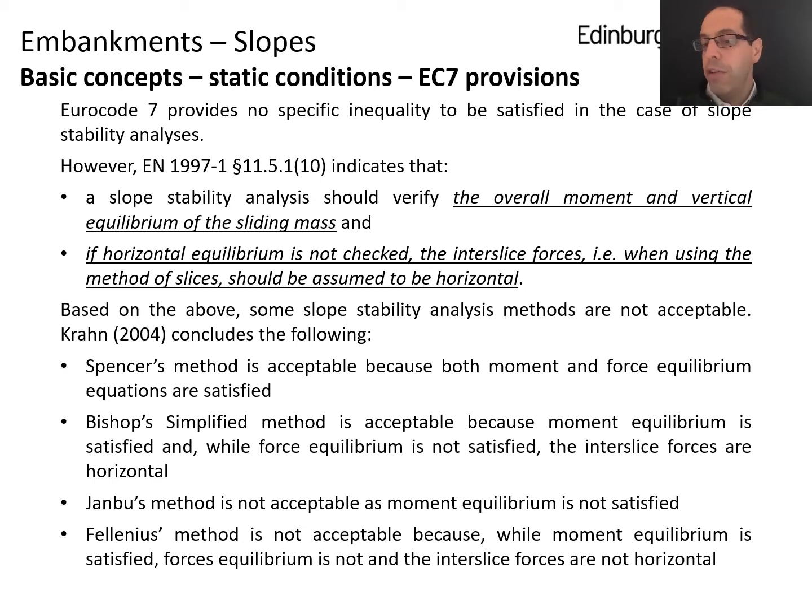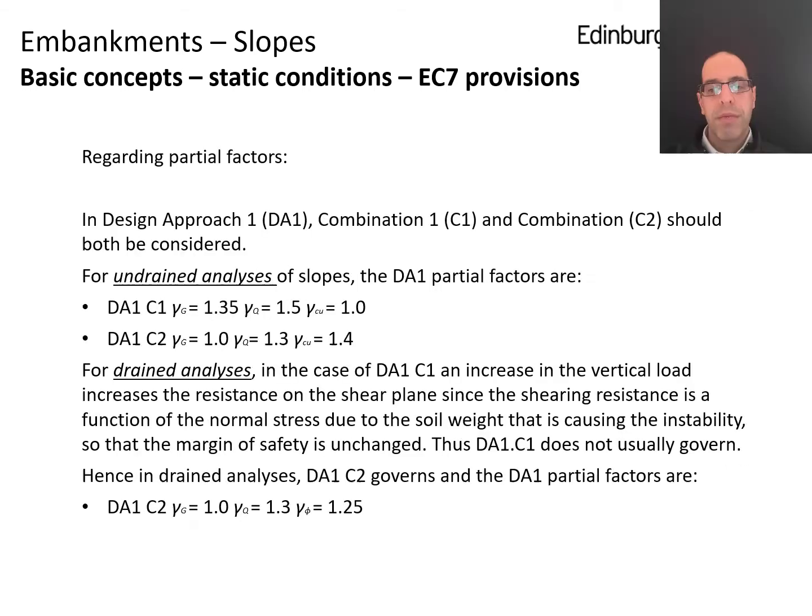Because again, Fellenius' method, the Swedish method, was the method that you could use for any shape of failure surface. And remember how we started the lecture today? We have to consider failure mechanisms that are not standard. So how do we solve that issue? And in particular, how do we deal with those failure mechanisms for slopes under dynamic conditions? That is what Eurocode 8 will tell us in the next slide.